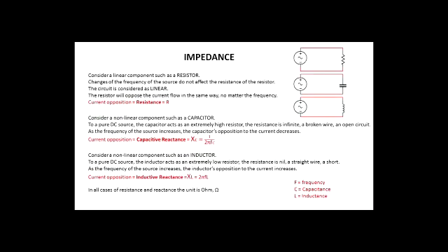When it comes to dealing with coaxial cables, one of the main specifications you're always going to hear about is the impedance. People are going to ask: what's the impedance for the coaxial cable? Which impedance do you need for this type of equipment? When they say impedance, what they really mean is something called characteristic impedance. There's a difference between impedance and characteristic impedance, and we're going to talk about that.